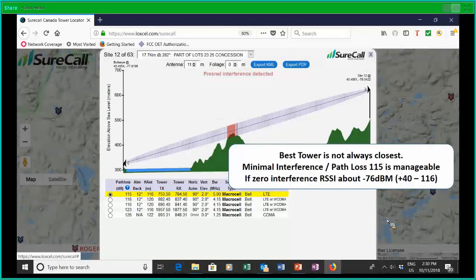If your customer happens to be fortunate and have direct line of sight to multiple cellular towers, your bias should be to recommend a tower that has the lowest path loss and a tower that offers the greatest number of channels for the target carrier. A path loss of 90 dB without hills in the way would suggest a very strong signal. A path loss of 130 dB without hills would be a weak signal.